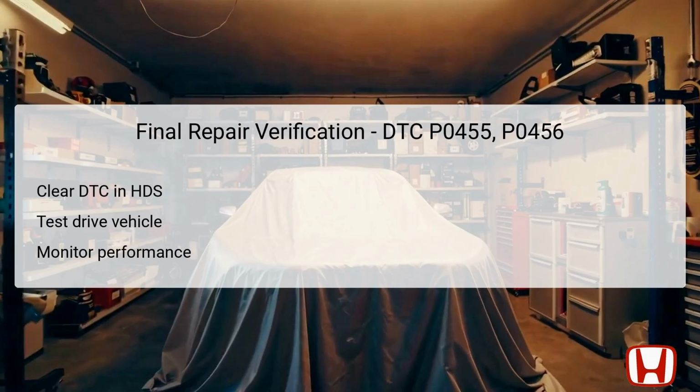Once repairs have been made, proceed to verify the effectiveness of the fix. To do this, clear the diagnostic trouble codes using the Honda Diagnostic System, HDS, and conduct a test drive to ensure that the system is functioning properly. Monitor the vehicle's performance closely, paying special attention to the check engine light and any unusual symptoms that may arise. The final verification process is essential to ensure that the repairs conducted have effectively resolved the fault and restored the system to its expected functional capacity.